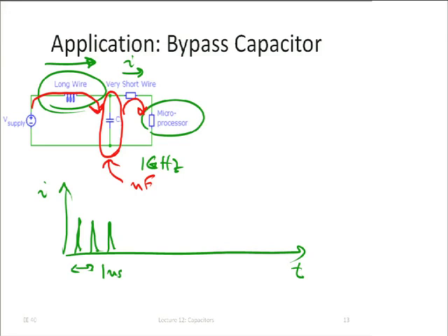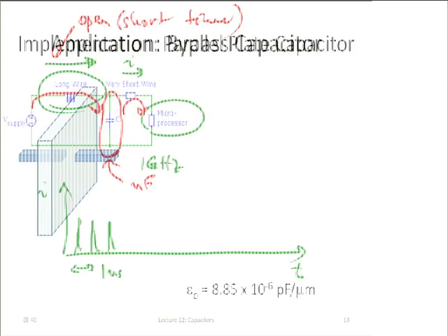So if the circuit was supplied for a long time, the capacitor will act like an open circuit, right? The capacitor acts like an open over the long time. But over a short time, the capacitor acts like a short with a voltage source in series, very low impedance. So time really comes into play here. Let's look at another example.